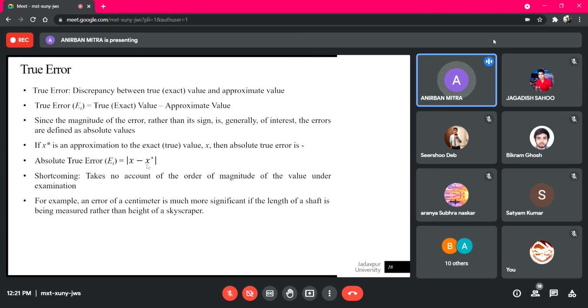So in case of stress, deviation of 1 unit is not that much. Instead of 700 MPa, you probably consider 701 MPa. That error will not be too much. But the true error is still 1. In case of strains, if you have a true error equal to 1 unit, where the order of magnitude of the actual strain values is 10 to the power minus 3 or 10 to the power minus 4, then that is a huge error.